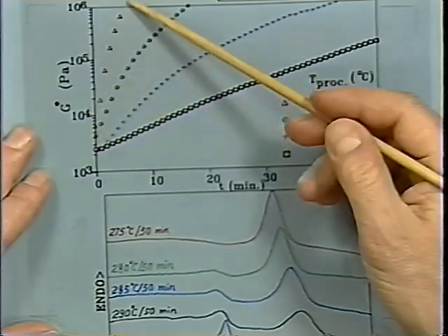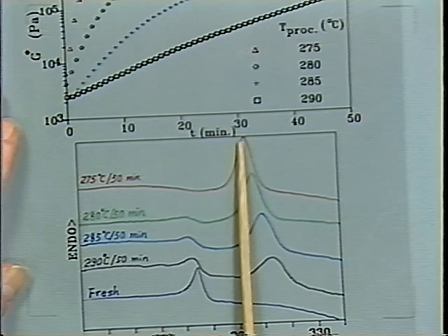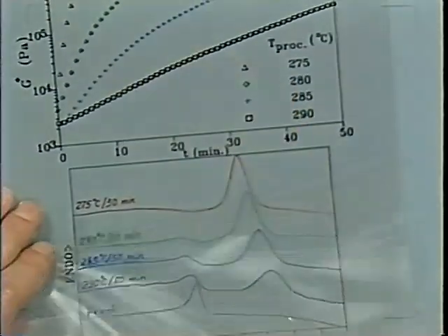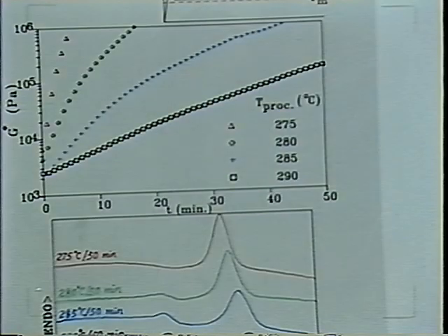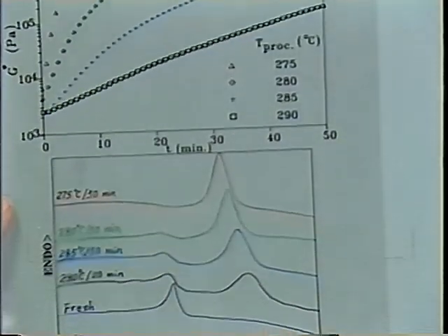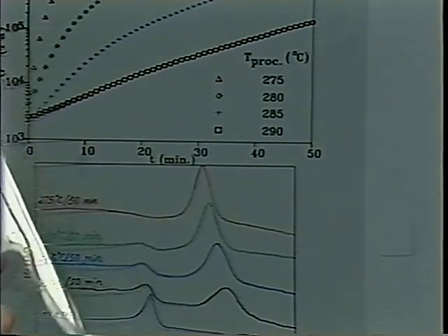If you do that at very high speed, the order will not be as high, so the new melting temperature will not be extremely high, but it's still above 300 degrees C. While if you do things more slowly, you get more perfect order, and you get higher melting temperatures. There's an additional spacing with this new order. There's an initial spacing in the wax pattern, a 3.8 angstrom spacing, and that's associated with whatever order is coming in. It's the same spacing as one of the components, so it's not completely clear what's happening.